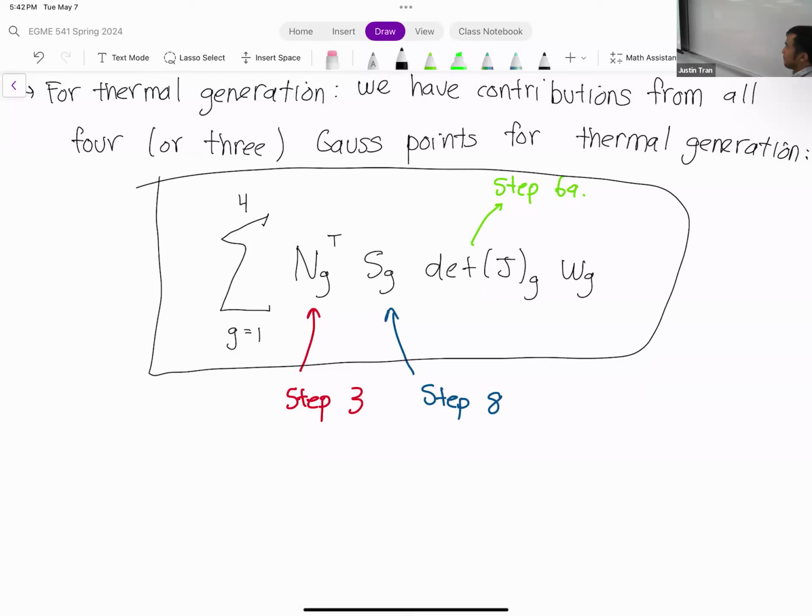So that's part 2 of the project right there. Part 2 is to take your contribution. If you're following this algorithm exactly, you already have it computed. You just need to sum it up and add it to the element forcing. This FE is equal to this.